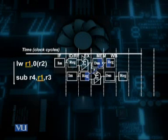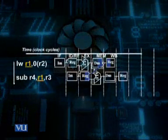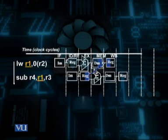Now, at this stage, I would like to explain how we can design the hardware for the bypass circuit. For this purpose, let us have a look at this diagram once again, where you can see that the pipeline register for the execution and memory stage contains the values of RS, RT, and RD for the first instruction.